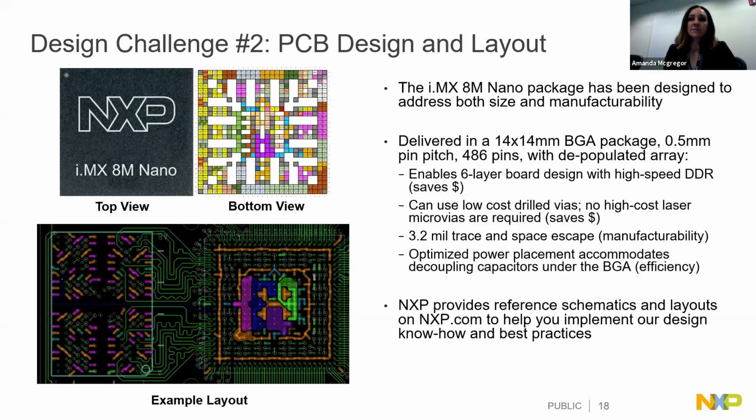Standard trace and space escape routing, so it's not going to push you to very boutique PCB manufacturers. It's a standard methodology that is used everywhere. And then we've also optimized the power placement of the ball map to help you put the discrete components, for example the decoupling capacitors, underneath the package to create even more space savings for your product.